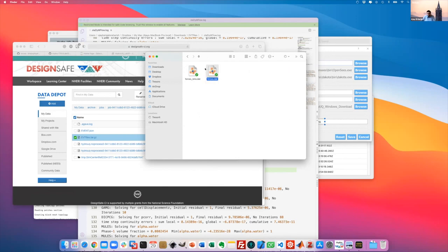It takes the entire building, or a face of the building, as one single patch, and it's going to integrate the pressure over this patch. So that's what forces would be. Forces_bins basically takes each of these floors as one single patch and integrates. So you get some kind of a floor loading. I think Quanchi will talk a lot more about it, so I'll leave that to Quanchi to discuss in the next session.